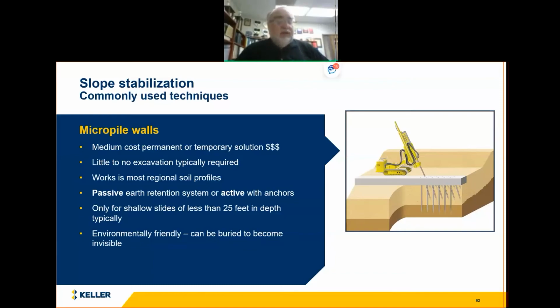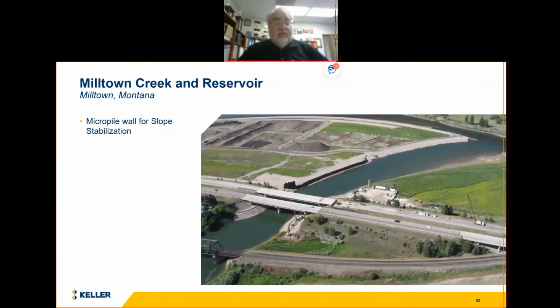In my experience, it only works for slides less than about 25 feet deep. When you add tiebacks, you can go to 30 to 35 feet, but it gets a lot more expensive. So just like the anchored block solution, it is very environmentally friendly, it can be buried and invisible.